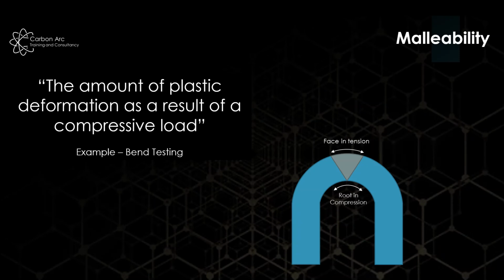So we would be testing the face side of the weld. This would check malleability. It would also check if we have any lack of sidewall fusion defects, which will allow that face to be ripped apart because of a welding defect.